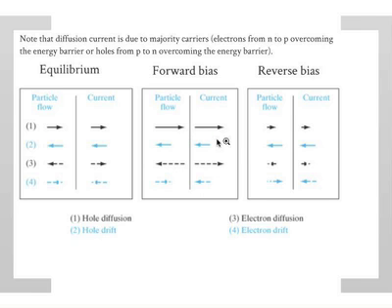So you can see, if I want to calculate current, all I need to do is add up all these components, just like we did before. Remember, we did this for a regular semiconductor, no junctions or anything, just N-type or P-type. We added up these four components. Basically the same thing. As I said before, if you're able to calculate current in a homogeneous semiconductor, you can apply it to any device. Before we jump into the equations, I want you to be fairly clear on this picture. The picture is much more important than the equations, in my opinion.